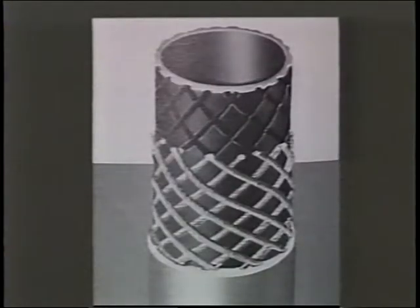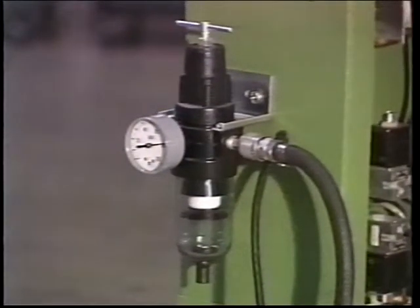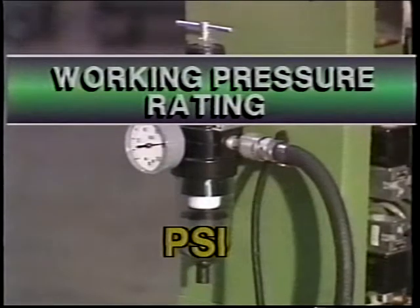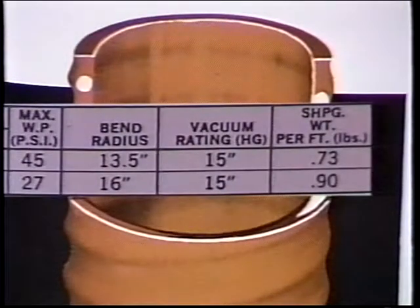The reinforcement of the hose, as said previously, is generally a fabric, yarn, or wire, or a combination of these materials. The strength of a hose reinforcement in regards to its ability to withstand internal pressure is referred to as its working pressure rating, expressed in pounds per square inch. This is often abbreviated as PSI. The strength of the hose in regards to its ability to withstand internal vacuum or suction is referred to as its suction or vacuum rating.